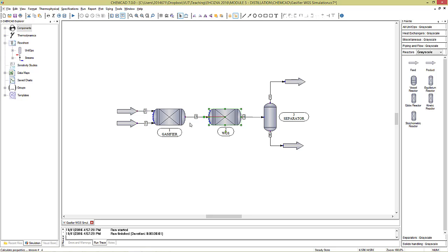I would need to see that in your flow sheet that you produce. That heat exchanger is going to use cooling water. I would need to see the flows of the cooling water, the flows of the utilities. That's what your flow sheet needs to look like. This one, I'm just guiding you through the flow sheet synthesis. For your flow sheet, you need to specify everything.